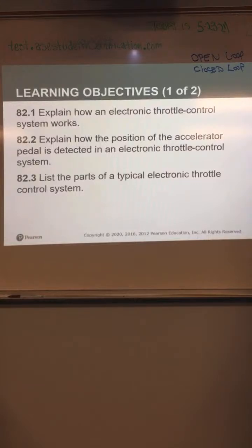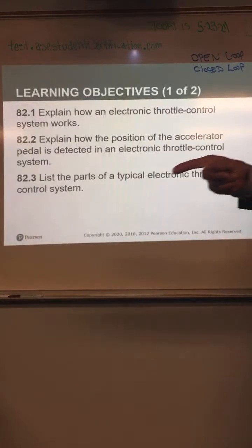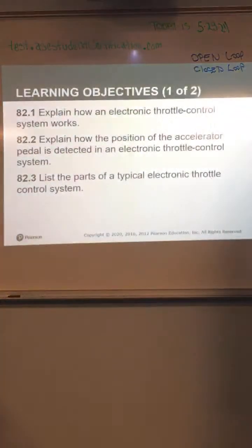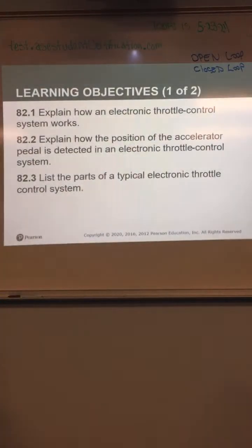Normally the boost is blowing air right into the throttle body, with hoses and coolant and stuff. Yeah, that's the turbo though. For a supercharger, then it's behind the throttle instead of in front of it. So it's like a blow through or a pull through kind of thing.